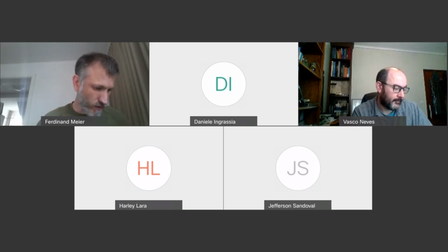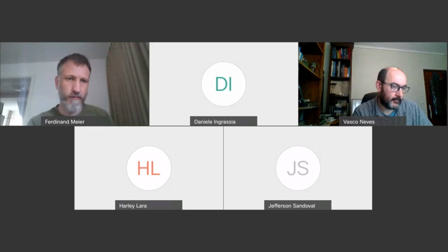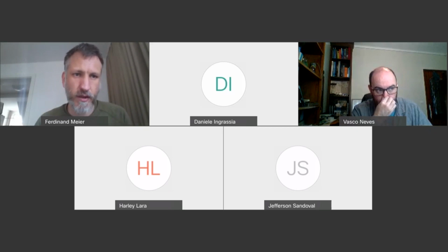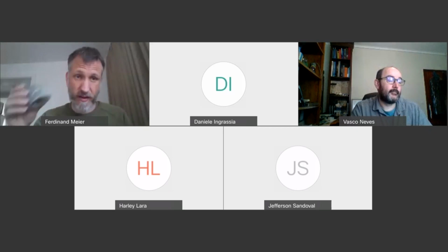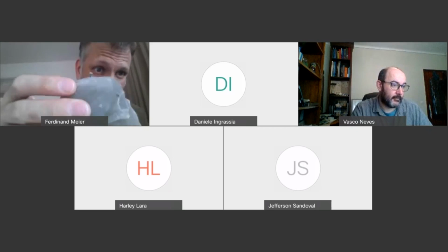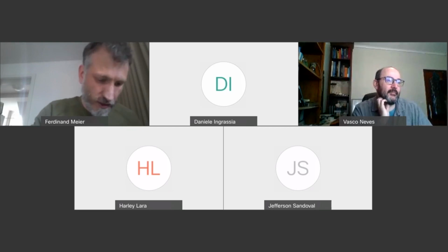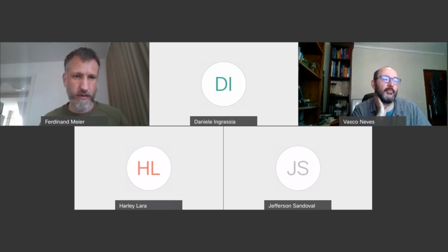So yeah, but for Neil, we have to 3D mill a mold. It's not okay to just copy a piece, and we have to make a silicone positive and a resin negative. But the resin negative, of course, can be from gypsum or from chocolate or from any other material that you might want to cast. Wax is very easy. So if you want to make some awesome candles, like this is actually a candle now, that's a very easy way to go, and also a very cheap way to go, because you can buy a kilo of paraffin wax for like a few euros. It's very cheap.